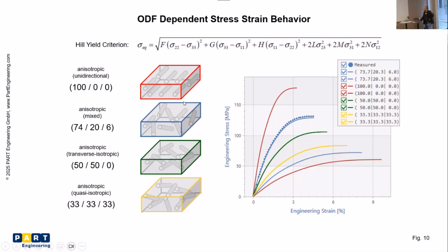And for the 100% one, of course, this would pretty much cover the whole range of the material itself, because there can't be anything higher than in 100% orientation, the stiffness and strength in this direction, if you load it in this direction, as well as there can't be any lower than this if you would put a load on such an element perpendicular to the main direction. Then, of course, it would be the weakest performance.